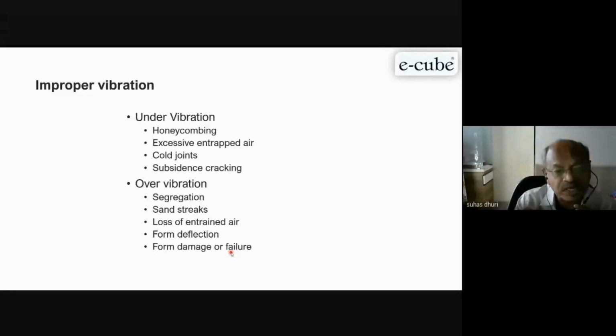So concrete has to be vibrated, not only the reinforcement. Or sometimes they put the vibrator on the shuttering. It will definitely damage the shuttering, and there is a possibility of failure. So this precaution has to be taken for the vibration. It is because we don't give proper training to the workers who are handling these materials, vibrators, finishing or compaction.